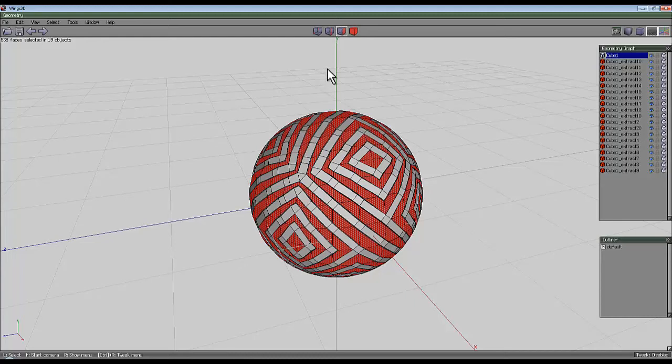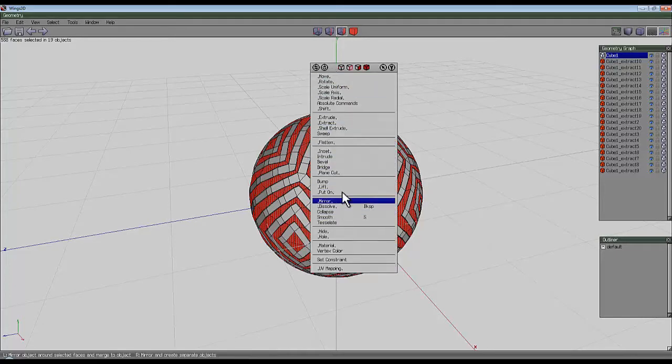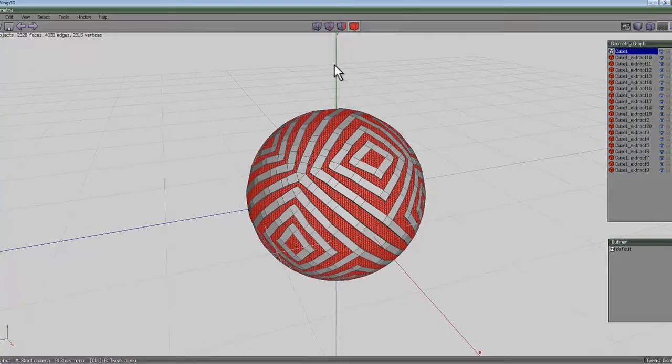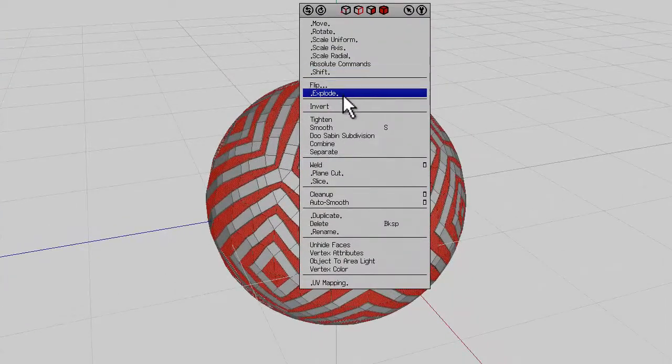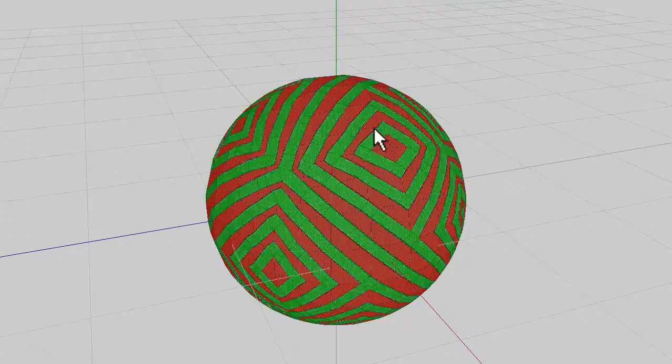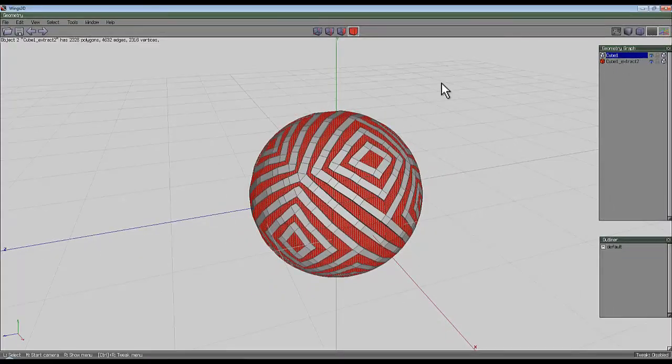So what I want to do to simplify my object is just combine all those new bits into one new object. So right click and it'll be in here somewhere if I'm under the right mode. So that's the face mode. I need the solid mode, that's the entire object mode, and then I just find combine, there we go. So now I've got two objects to deal with.